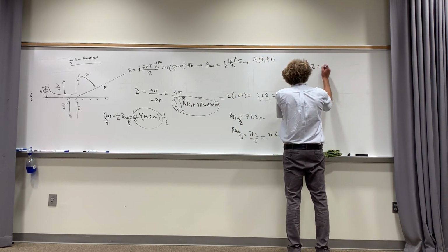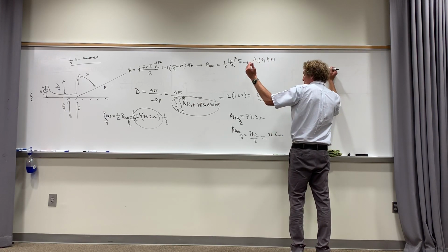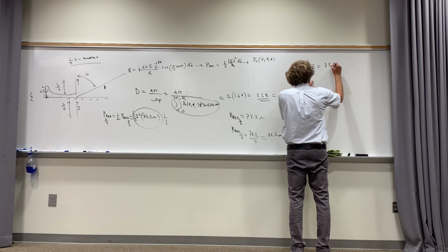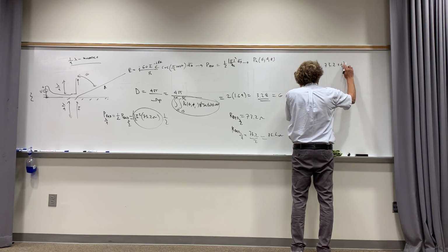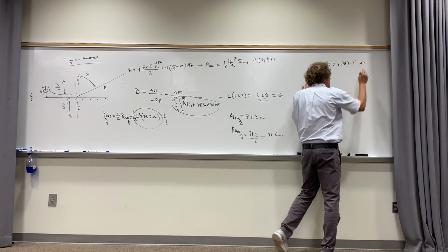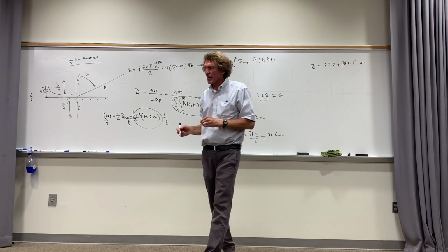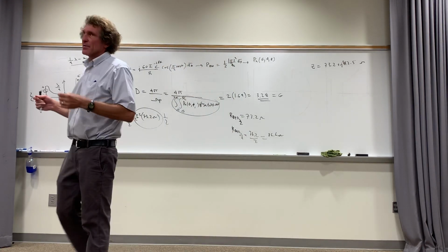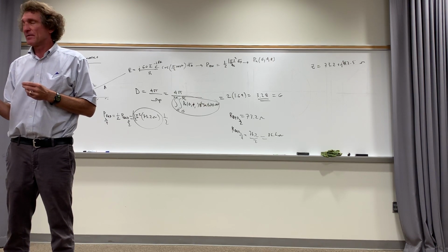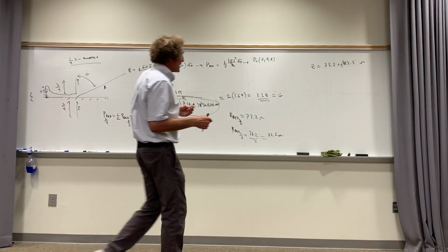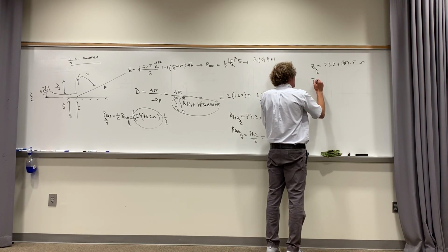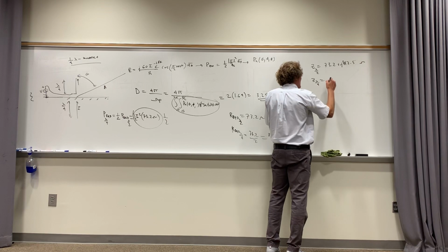Now, something else I'm going to say, that for an exact half-wave dipole, you remember the Z, the total, with the radiation resistance plus the reactance, was equal to 73.2 plus j42.5 ohms. Do y'all remember that? That's if it's exactly a half-wave dipole, we didn't shorten it to whatever it was, 0.485 lambda, right? If it's exactly that, then the actual Z, and this is for a lambda over 2 dipole, the Z for the lambda over 4 monopole is simply half that.